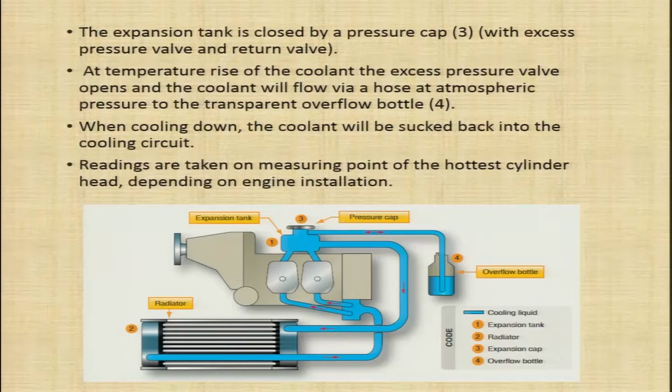Now, when cooling down, when the temperature reduces, the coolant will be sucked back into the cooling circuit. As the temperature reduces, the coolant goes back into the system. We have seen earlier that your cylinder head temperature is measured at the hottest cylinder head, depending on the engine installation. But some of the modern engines are being equipped with cylinder head temperature sensors on all the cylinders, so that we have the CHT measurement for each cylinder.